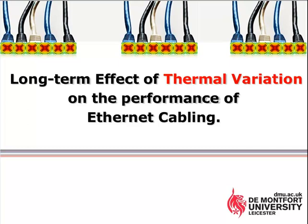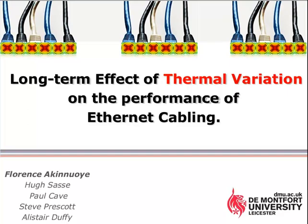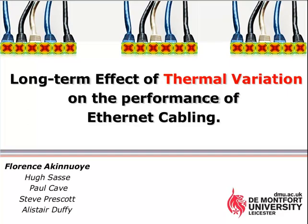The main thrust of today's presentation is to look at the immediate effect of temperature and the long-term effect of thermal variation on the performance of balanced UTP cables that are currently used for power over Ethernet applications. We will also be looking at the effect of temperature and the effect of thermal variation on the performance of different dielectrics that are used for conductor insulation in data-grade cabling. So today, we're going to start by looking at the motivations for these studies.